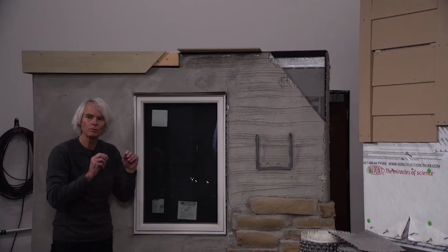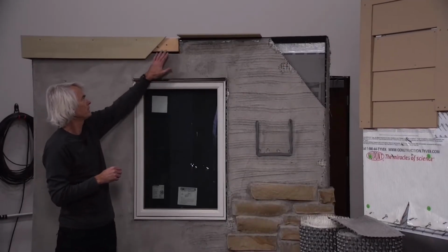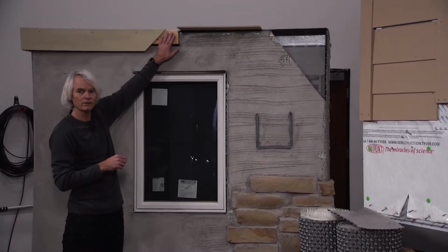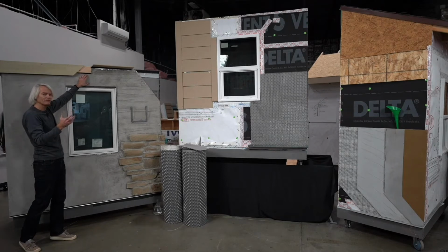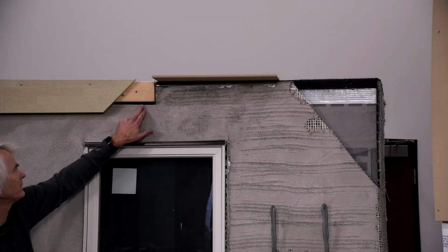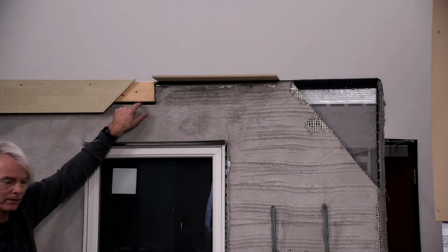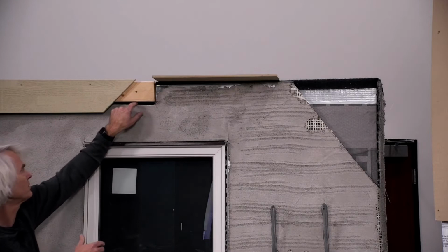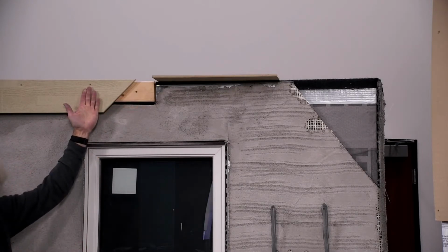So I'll just show 2 details that we've pulled off here to demonstrate. Number one is we've got a piece of blocking here. This is a 2x4 block. And you can see our casing bead here, which is held short by about 1/2 inch from that block. And we're about 1/2 inch to 5/8 inch thick on our stucco product itself. Up here we can see we've got this vent. There's a bug screen product that's included with this system as well. And so we've got that installed, and then a trim board that's been installed here.